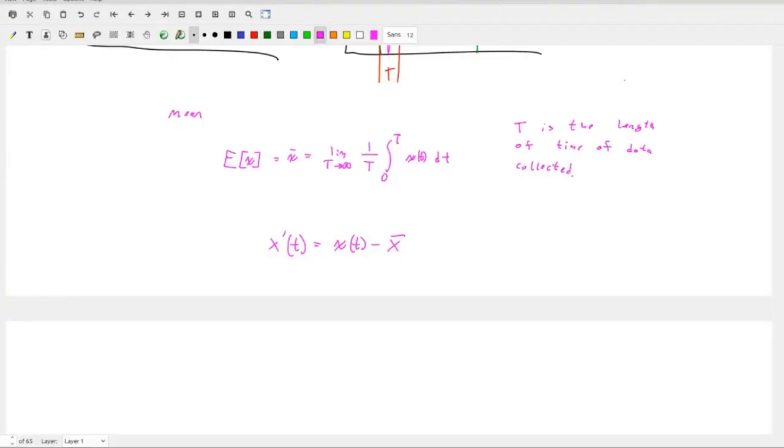As we mentioned before, it's important to consider whether the input is stationary. And this is the debate we have every Monday, right? What is a stationary signal? A signal is stationary if its statistical properties, usually expressed as its mean, do not change with time. So a stationary signal may look completely random, but if our properties are constant or relatively constant through time, then it's a stationary signal.